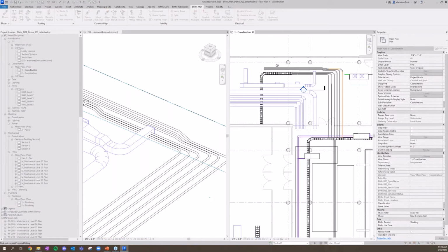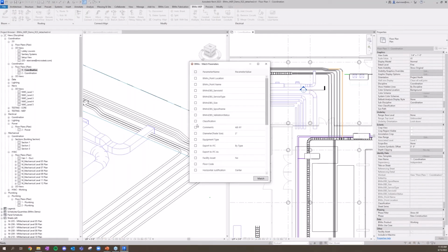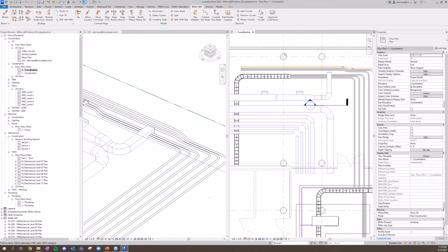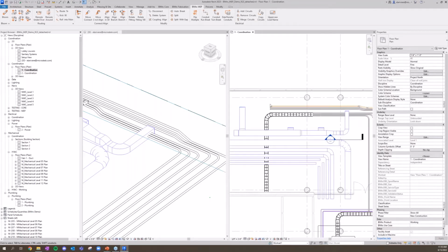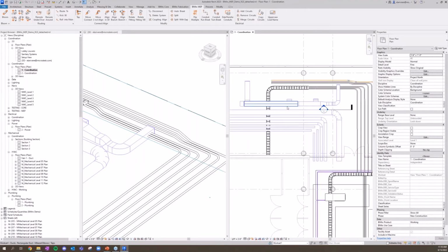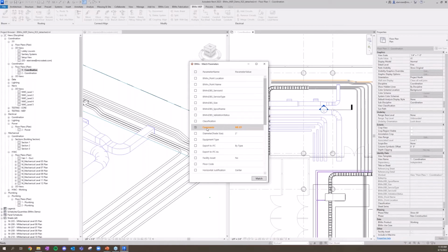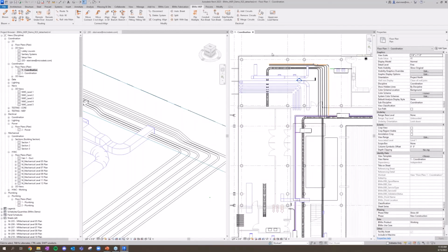Simply select the first conduit run and the last conduit run, and you only have to do this step once. The 2 parameters you want to track, or more, as many as you'd like. And there we go. Those values are passed through, right? Very, very quick. And what's extra cool is the next time you run that command, it is already tracking those values for you and will continue to track them until you close out of Revit. So very, very quick process for us to get in there, get those conduit parameters and all those MEP settings.